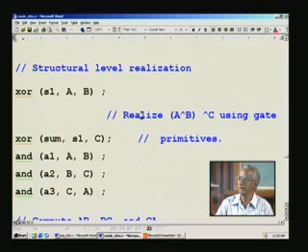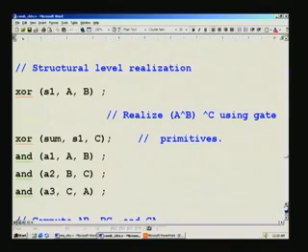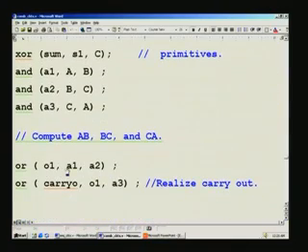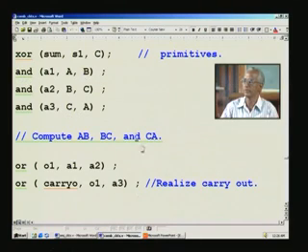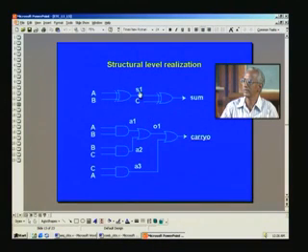And this is what is realized here, exclusive OR of 3 inputs. And then A, B, B, C, C, A, the majority logic for the output as such here. And these are all the intermediate signals S1, A1 through A3, O1 etc. here. And this has exactly the same meaning as exclusive OR. So, always output followed by the inputs: AND operation for a 2 input AND operation, 2 input OR operation here, and that is what you had here. See, these are all S1, A1 through A3, O1, precisely the intermediate outputs that we have used.